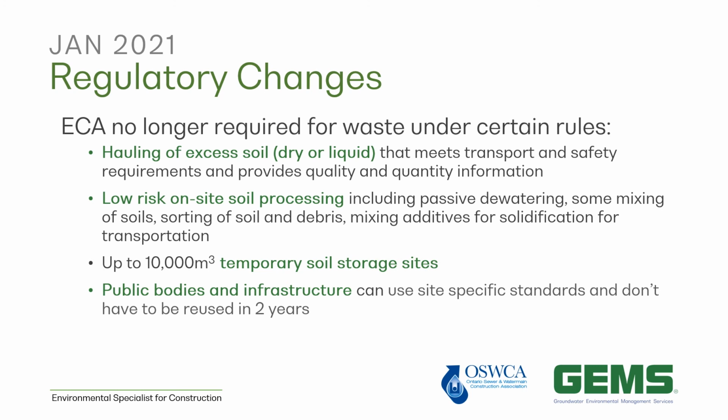If you are moving up to 10,000 cubic meters to a temporary soil storage site, you do not require an ECA. And any public bodies or infrastructure projects that are happening are able to use site-specific standards, and that material on those projects doesn't have to be reused right away. You have up to 2 years to reuse it. So if you're doing a large infrastructure project, you have the ability to keep working with that soil without having an ECA, and you have 2 years to move that soil around. It doesn't have to happen right away.